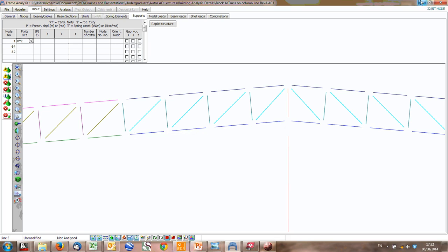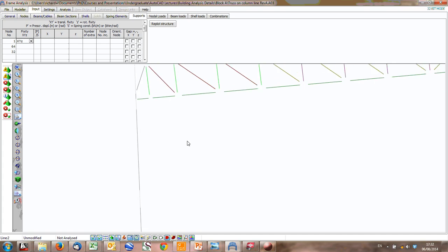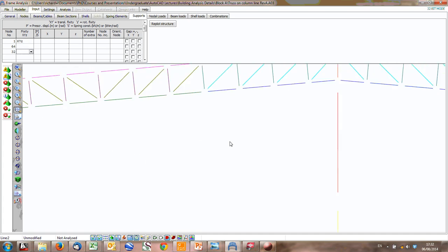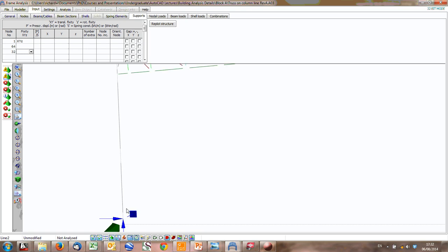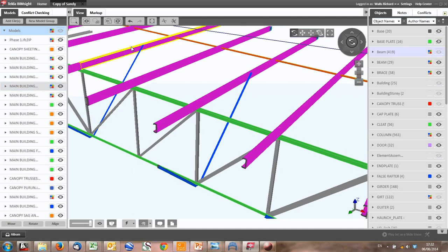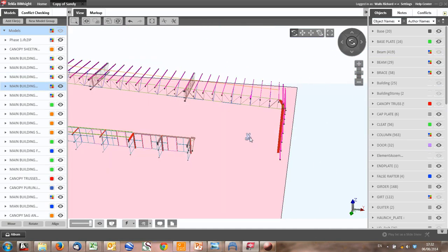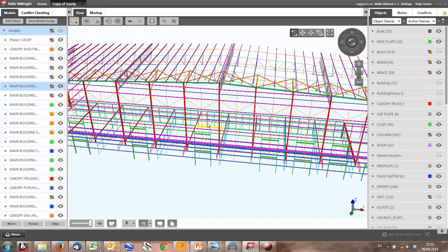So have a look at all these factors, and the same thing with the column. You might think the effective length of this column is from there to there, or from there to there. But just see what prevents it buckling sideways. And that's where either you've got the girths or your knee braces. So it depends also if it's the inner flange or the outer flange. So all these things you have to consider when doing a design and carefully take your loads through.